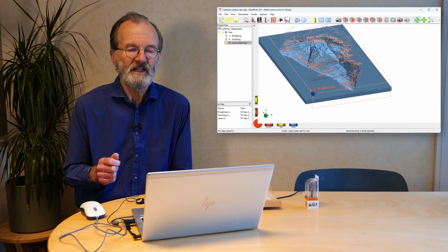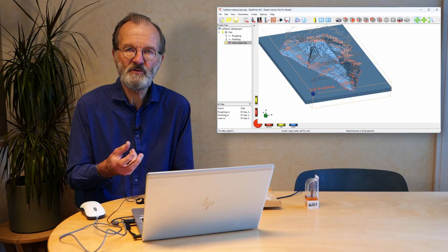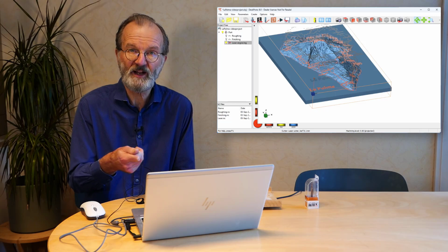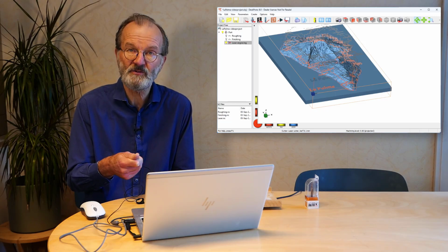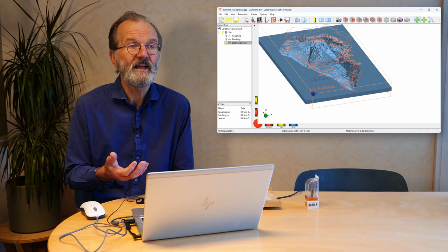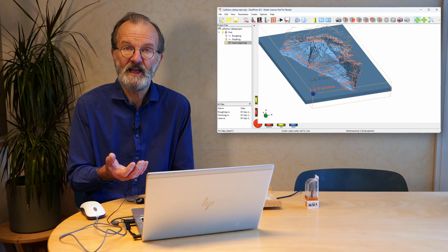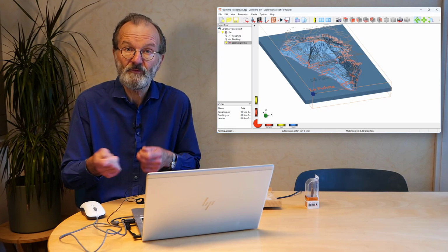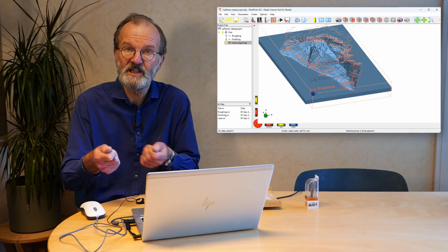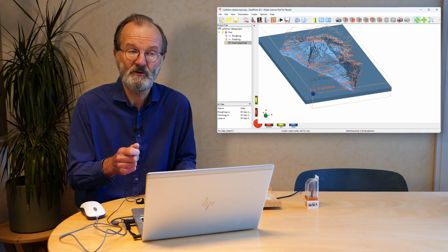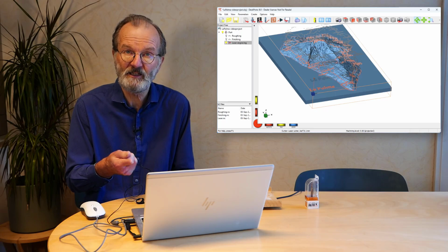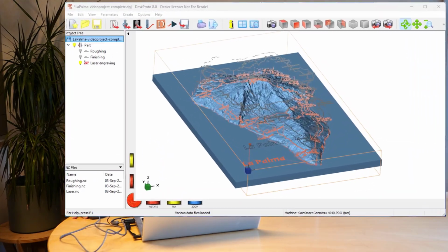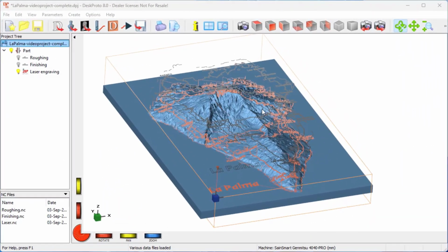One more detail. In the project that I just showed you, I loaded two vector data files, and then I transformed the vector data, so scale and pan, to match the geometry. I did that using the part parameters, and the part parameters are valid for all vector curves. So what if a different transformation, different scaling is needed for each file? Well, then I can also apply the scaling, panning, etc. per vector file. I will quickly show you how to do that. It's pretty simple once you know how.